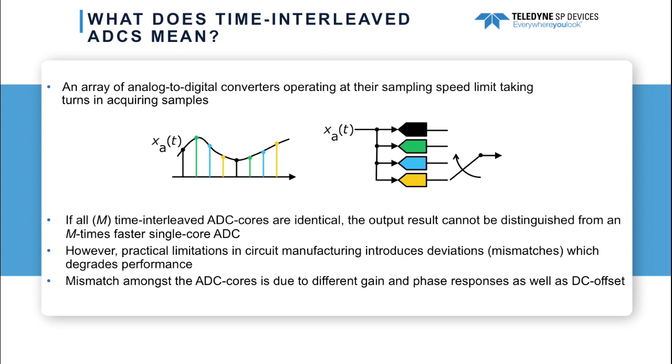There are, however, two main practical limitations. One limitation is the input bandwidth, which actually tends to reduce when increasing the amount of ADC cores. Adding more ADCs means adding more parasitic capacitance to the input node, and for a targeted input signal swing, the input bandwidth will be limited. This makes the time-interleaved system suitable only for oversampled applications for the use of a large number of ADCs in the array. Achieving sufficient input bandwidths in the time-interleaved ADC structure is typically accomplished by using amplifiers or sample-and-hold circuitry in the front-end design.